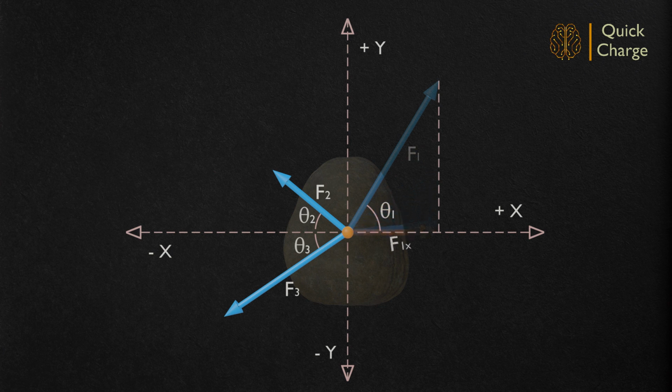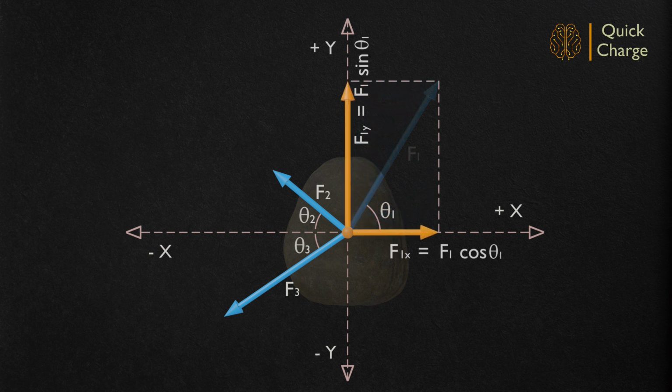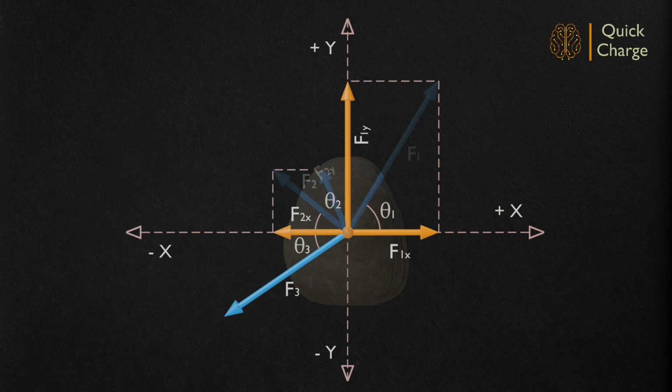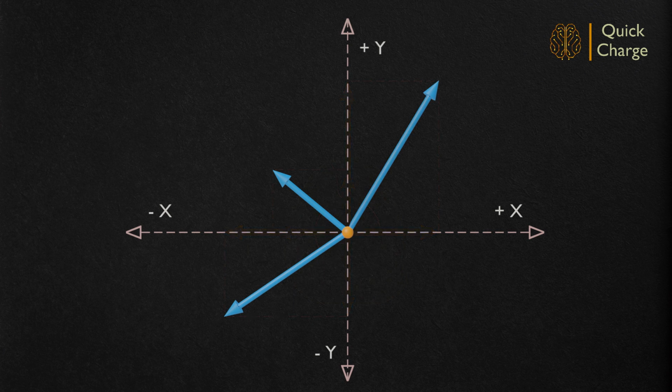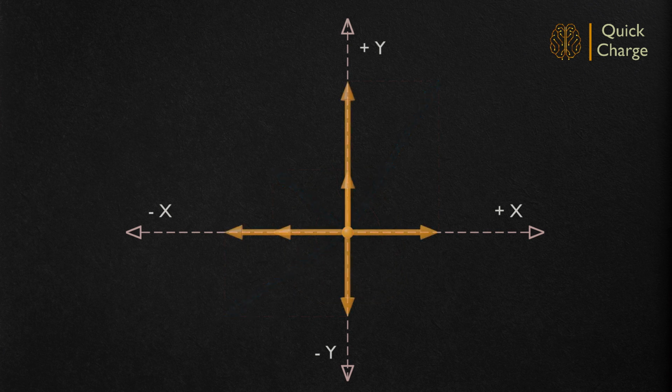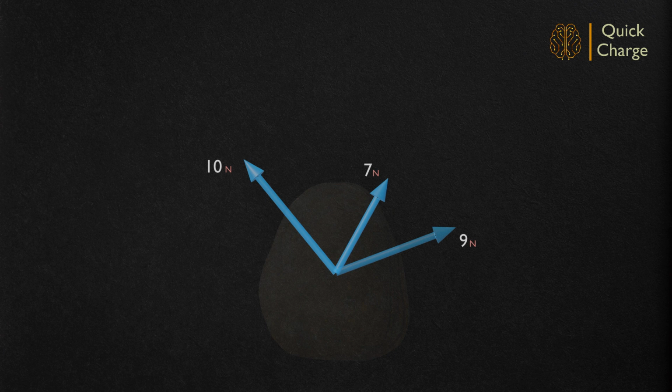Resolution of forces is opposite in sense to composition of forces. However, this will ease the composition process for complex force systems. The basic idea of method of resolution is splitting forces in any orientation into components along two mutually perpendicular axes. Let us redo the sample problem from the earlier module using method of resolution.